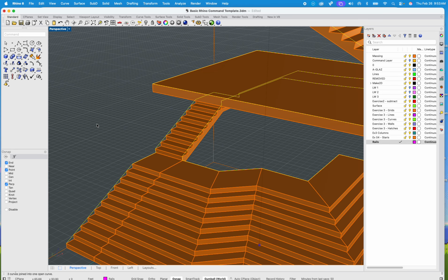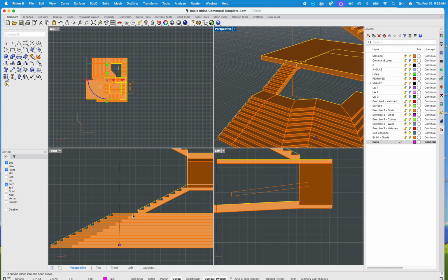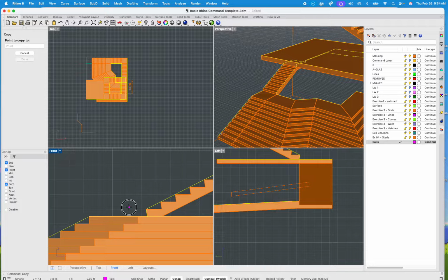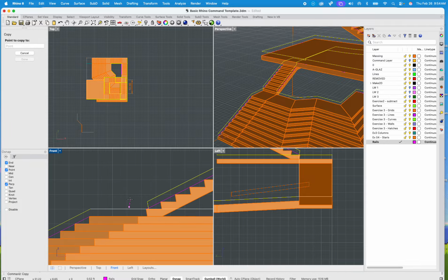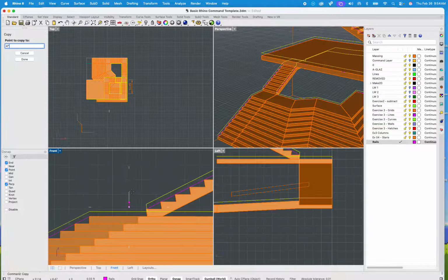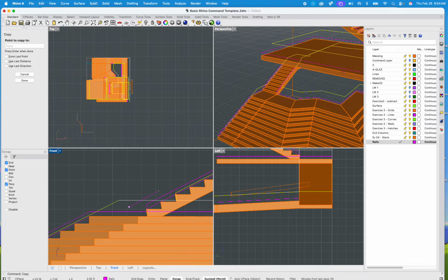Now, as you can imagine, we could take that, and if you know anything, of course, from Graphics 1 or Graphics 2, we know that we need at least 4 inches of space. It's the ball test, right? Escamilla usually talks about it. It's so that infants, of course, I don't know why they're alone by the stairs, but there's a 4-inch difference there. So in our case, I'm going to copy it because I don't necessarily want to get rid of the first one. I'm going to hit 4 inches, shift, and click.